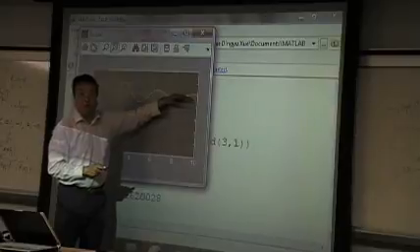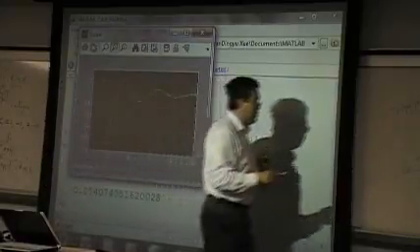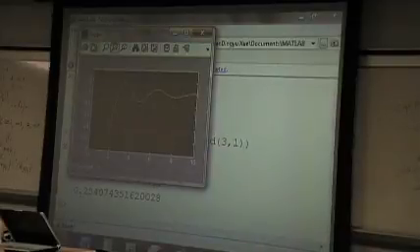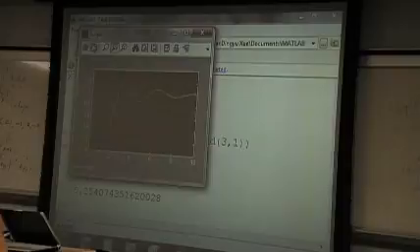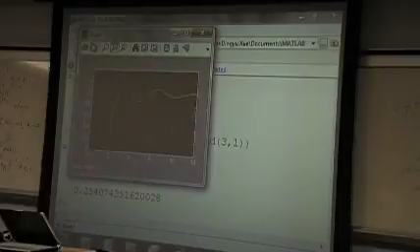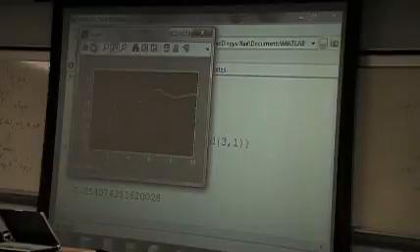That's why with the ISE criterion, you may get some oscillatory response like this. However, with the use of ITAE, you may have something like this. The initial response is slower, but the steady state is much better. So this is why we want to talk about the ITAE criterion rather than the ISE criterion.